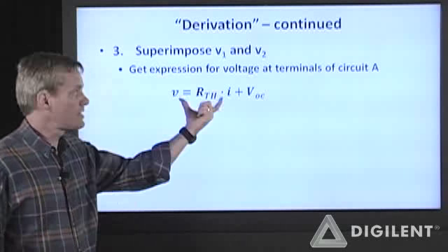In lecture 10, I listed the steps which are typically done to create a Thevenin equivalent circuit. I want to do that again, only maybe slightly more briefly. The first step is always to identify the circuit for which you want the Thevenin equivalent. You have to decide what your load is. You have to remove your load from that circuit. The remaining part of the circuit is what you're going to analyze. The terminals that the load was connected to are the terminals that you need to leave open to determine VOC, and the terminals that you need to look into to determine RTH.